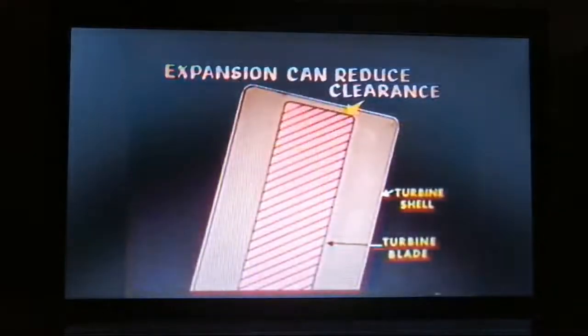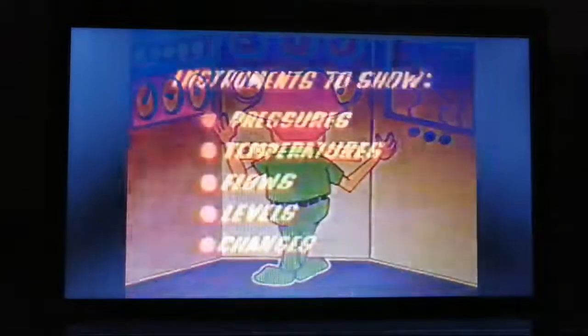Most materials, and especially metals, expand when they're heated. These electric wires are longer in hot weather and droop a bit more than they will when cold, and in large, closely fitted equipment, such as the steam turbine, expansion of heated inner elements can reduce the already close tolerances and endanger the entire machine as it rotates. Again, the operator has instruments to measure thermal expansion rates of equipment so he can prevent problems arising from excessively rapid startup or cool down.